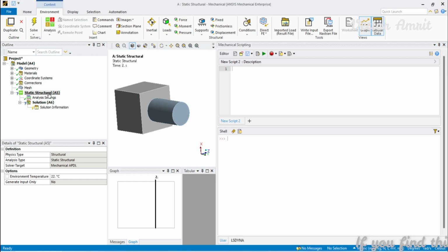So first thing is I have a static structural analysis. Let me just create one analysis A1. Not create, I mean assign it to a variable. So it will be model dot analysis and first index. So I will get A1. So this is the analysis here.